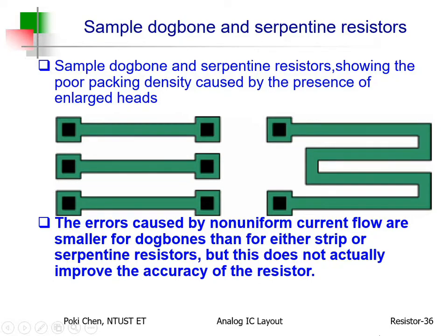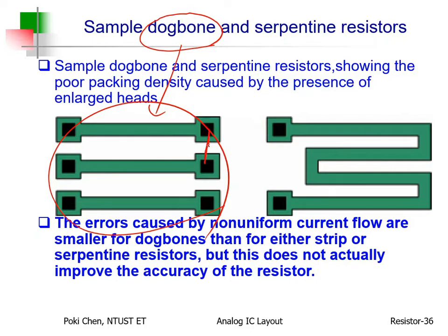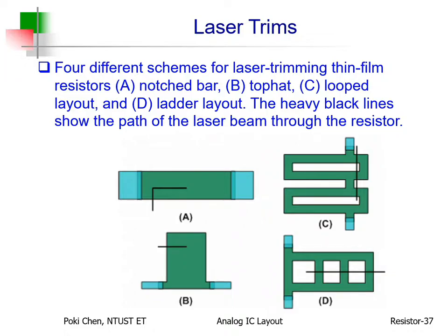Again, if you would like to enlarge the resistance, then you can consider dog bone, 狗骨头式的. Why? Because you can reduce the W to the minimum. Okay? It is totally possible. Yeah, and then again connect them in series to enhance the resistivity even further. However, serpentine is usually the one I wouldn't like to recommend because it is not accurate. Alright. We can go further.